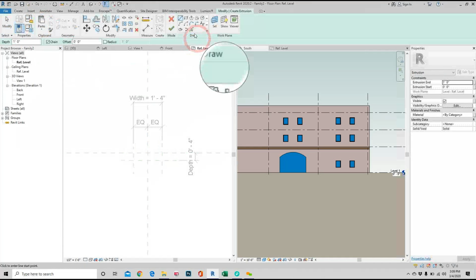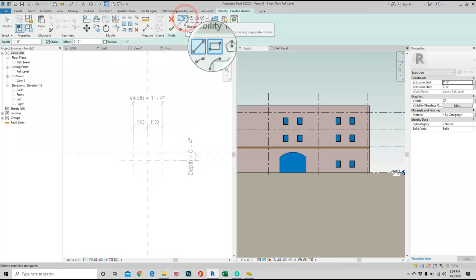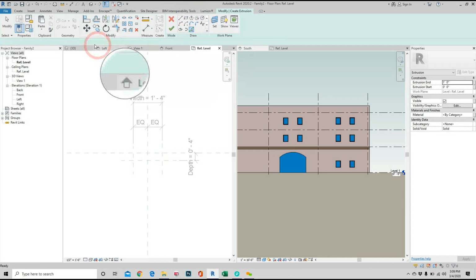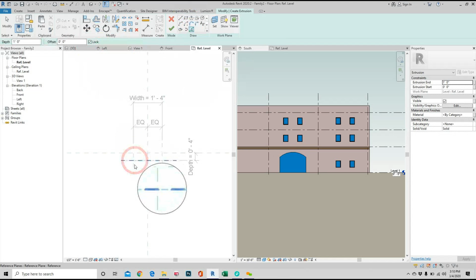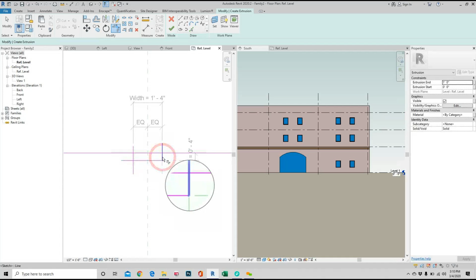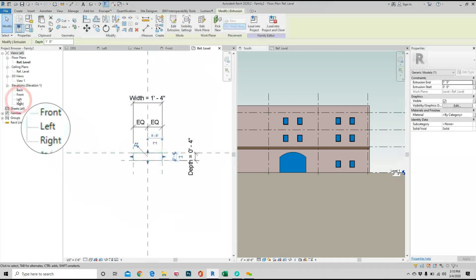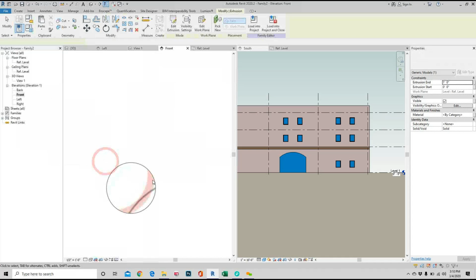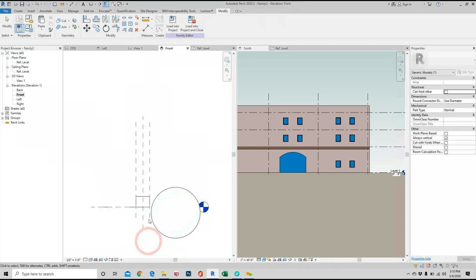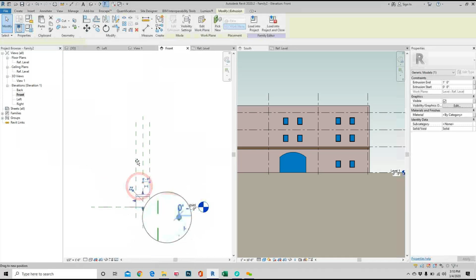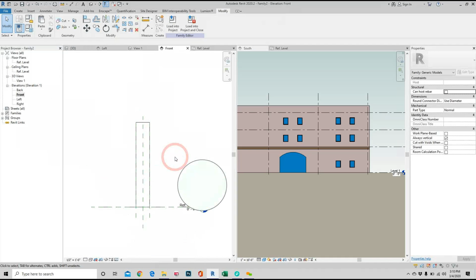Right, and that extrusion, what I like to do is I can pick lines if I wanted to. I can do rectangle right away. I'll pick lines and I'll lock it for now. Right, I want those lines to stay locked to this reference. So I just create this, click the 4 references, trim those lines really quick here. And once those are trimmed, I can finish this up, go to the elevation, and I'm going to be able to see the extrusion. All right, so that would be my pilaster.